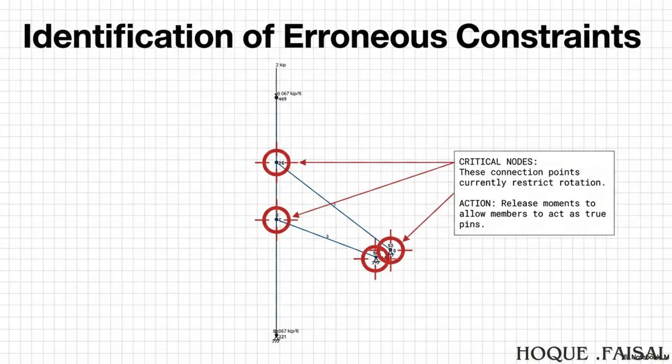So how do we fix this mess? Section 4 of our outline is the path to correction. And the supervisor doesn't just say, you're wrong. They offer a clear solution. They do. They offer two paths, actually. Option A is you can attempt to fix your third model by adjusting the nodes. Which means going back in, finding all those Fs, and carefully turning them into Rs in exactly the right places. Which is very risky. You have to be perfect. You have to know exactly which axis allows for rotation and which doesn't. You can easily make another more subtle mistake.